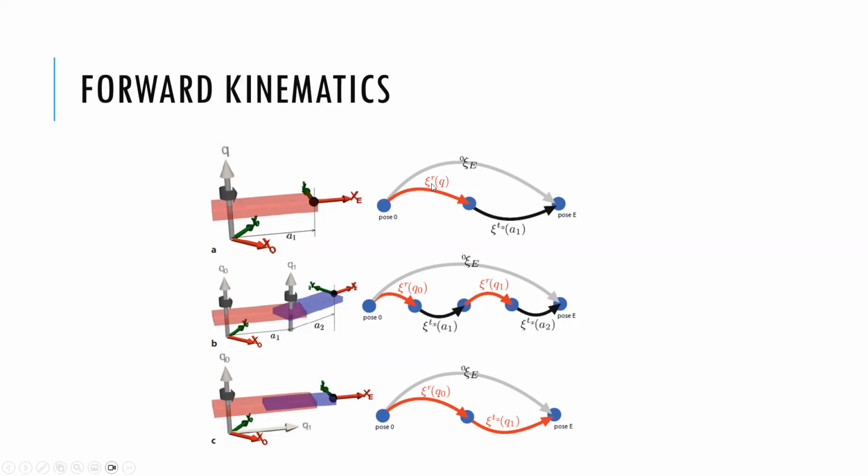So that is just the dot product of this. And here is from the base to the end effector. The end effector we can call E, and 0 we call the base or the origin. And here, with 2 degrees of freedom, I want to rotate, then translate. I'm on the red link, and then I want to get on the blue link. I want to rotate and then translate. And that chain is the same thing as the origin to the end effector here.